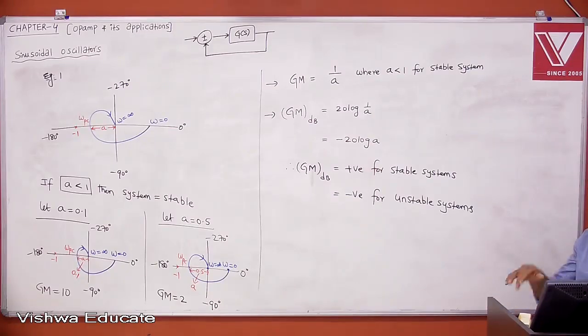But whatever it may be, if you calculate gain margin for the practical variations of K, and it is positive, you can say the system is stable. But we should have some margin, because after fabrication, if the expectation from modeling before fabrication is not correct and you get more variation of K practically after silicon, then we may enter an unstable scenario. That's why people try to have gain margin. Some margin we should have before fabrication.